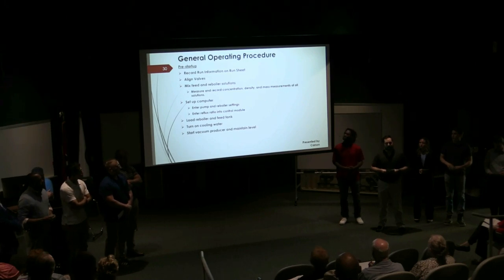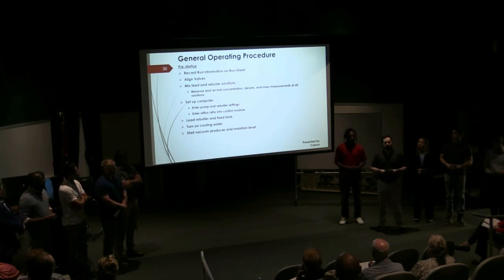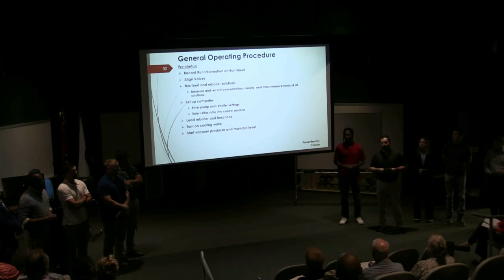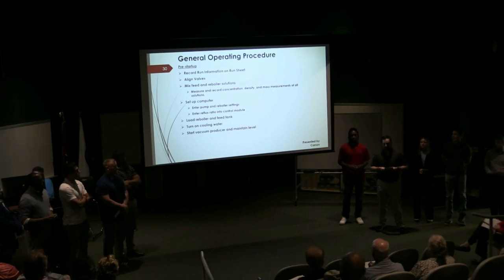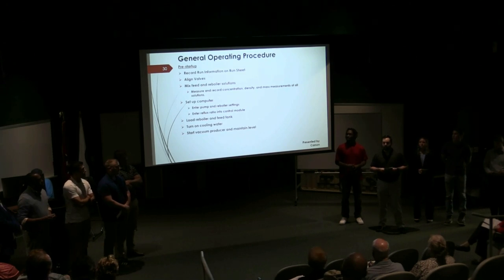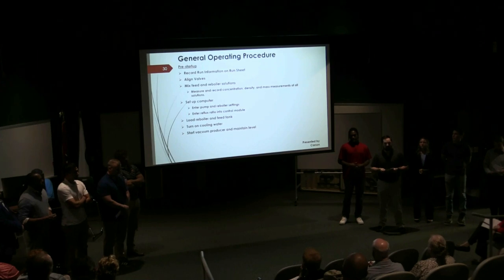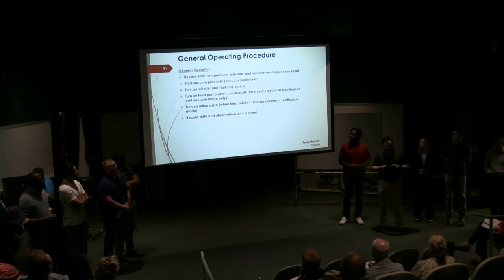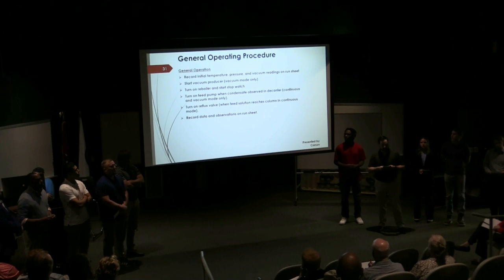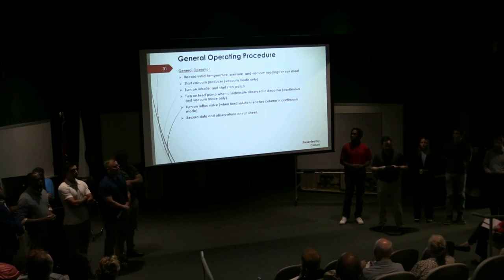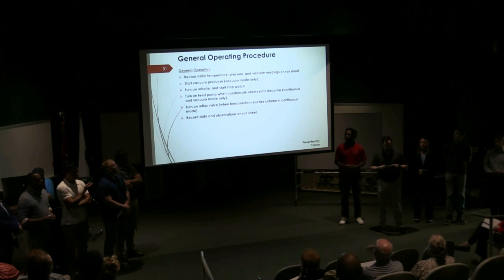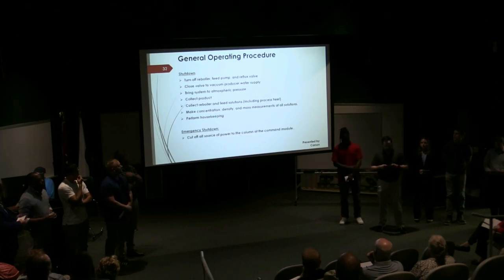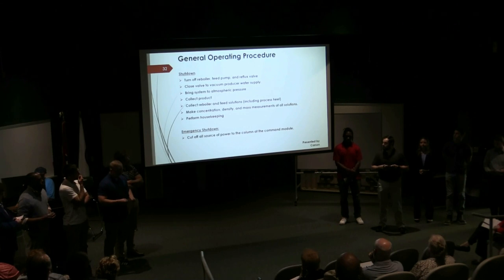Next, we'll be discussing some of our general operating procedures. We have 3 phases of our operation: pre-start, operation, and shutdown. During pre-start, we do things like aligning our valves, mixing our solutions, and setting up our computer. Next, in the operation phase, we record initial readings, turn on our reboiler and stopwatch, and turn on the reflux valve to initiate product collection and record our data. If we wanted to run in vacuum or continuous mode, we have steps for that also.